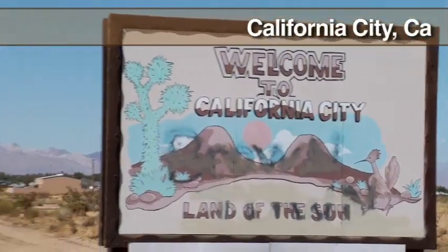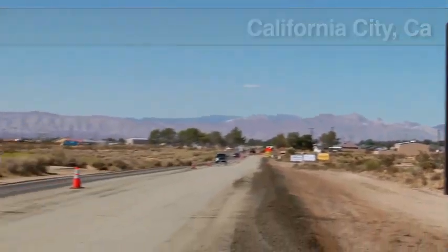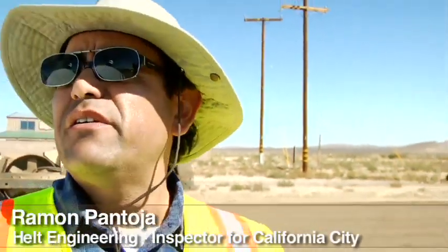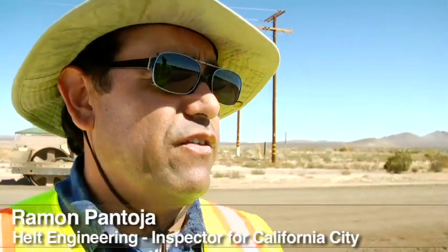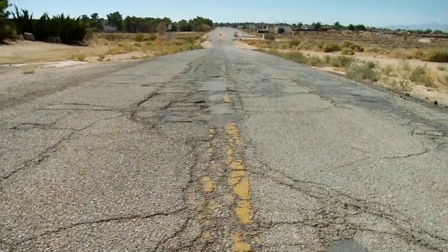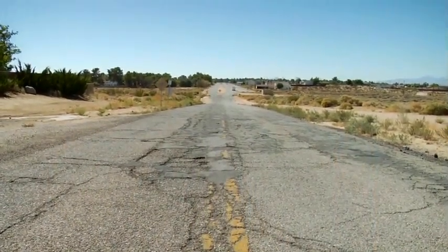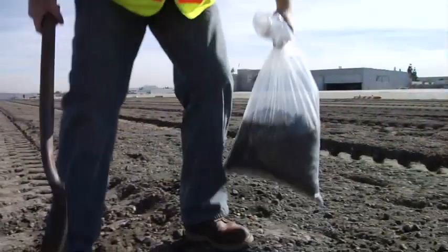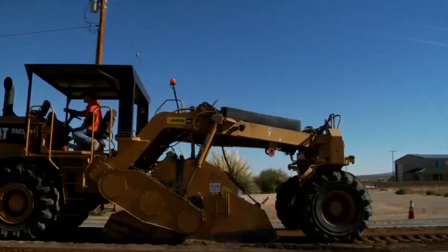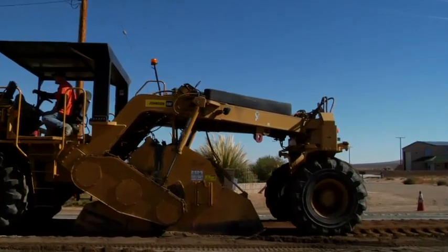This particular location was chosen because this is the perfect example of subgrade failure, which in this case, if we go with conventional construction, will be very expensive. Basically, over the years, the city, the agency, paved over desert mix. The soils engineers took samples of the existing pavement conditions, and therefore, they decided to recommend the FDR process. Now, with this process, our intention is to have a very strong foundation for this job.